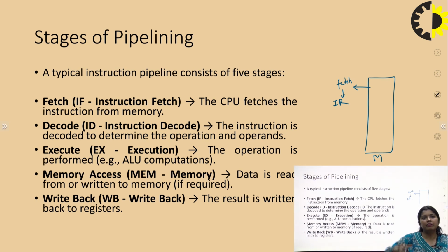So the CPU fetches the instructions from the memory and stores them in the instruction register, and generally the instruction register is 16-bit. Now the instruction register has the instruction, so now decode that instruction. Generally, decoding of the instruction will produce D0 to D7, or 8 operations. And the next stage of the pipeline is execution. Actually the operation is performed with ALU computation, whether plus, minus, add, divide, whatever the operations are, all the opcodes will be performed here in the execution phase.